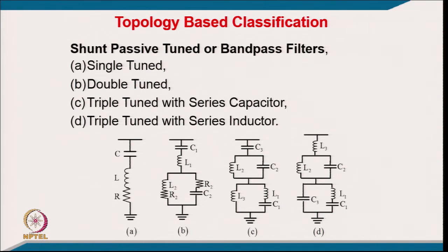So this resistance is normally kept very small, but it certainly helps in that it limits the harmonic current. To limit that current, normally we design a fifth harmonic filter corresponding to the 4.7th harmonic, not the fifth. There are two reasons. With aging of the components, the tuning should push from 4.7 towards the fifth. And a little detuning certainly limits the current.